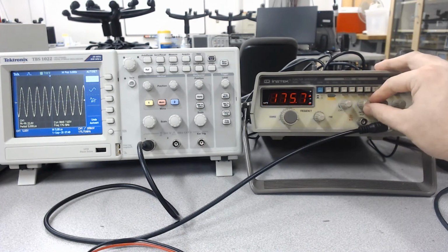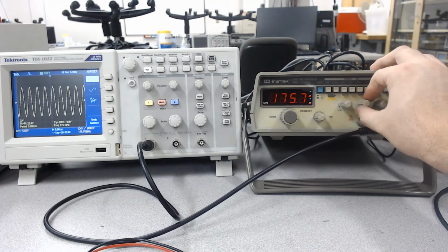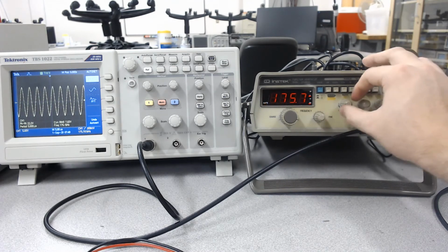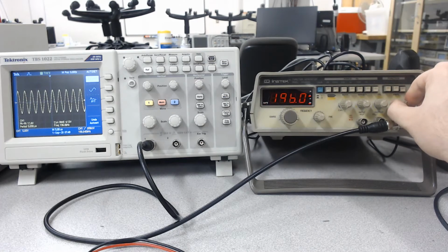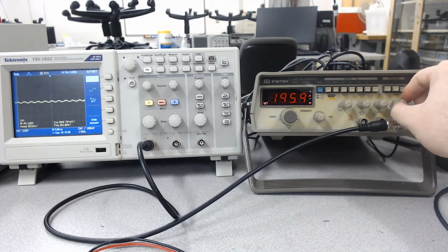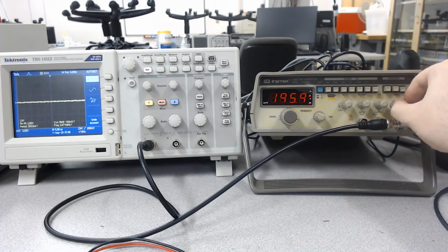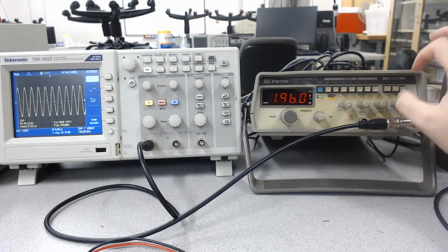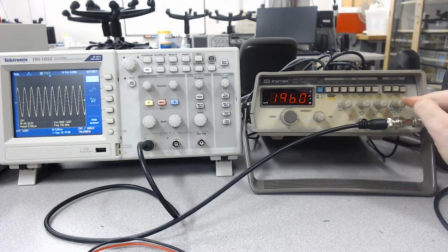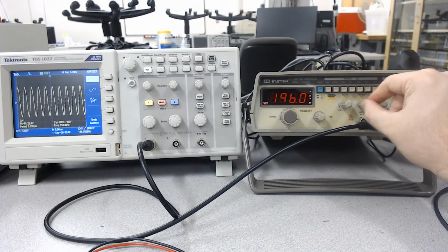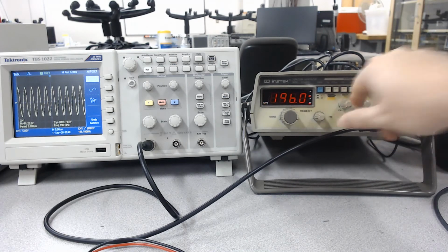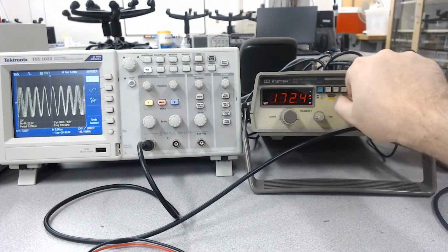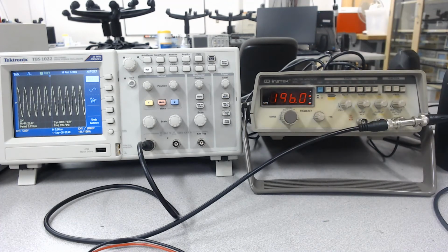The offset button only works if you twist it, and only if it's pulled out, whereas the duty cycle works either way, and the amplitude really only works when it's plugged in. If you pull it out, it just goes to 0 and doesn't really change too much at all. I guess it's changing very, very small magnitudes. So anyways, the amplitude should be plugged in when you're changing it, and the offset pulled out. The duty doesn't really matter. Not that we use the duty that much, but you need to make sure that it's turned all the way to the left, or else you could get some weird distortions or readings.